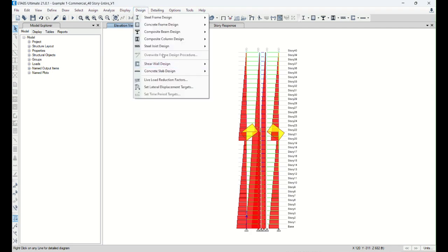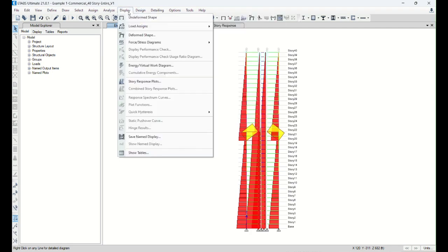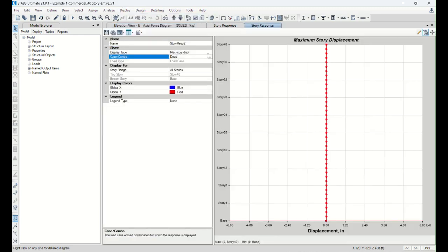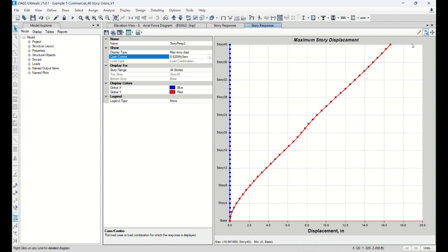Maybe I have to create a few more example slides, but here I display the plot. Let's check how much this outrigger contributes in the wind Y service wind load. So you initially had 21 inches, now it went down to 16 inches, right? So basically this outrigger is tying the column and working together with our wall. We gain some lateral stiffness, so that overall deflection reduced from 21 to about 17 or 16 inches.